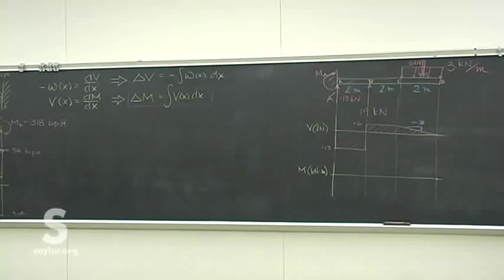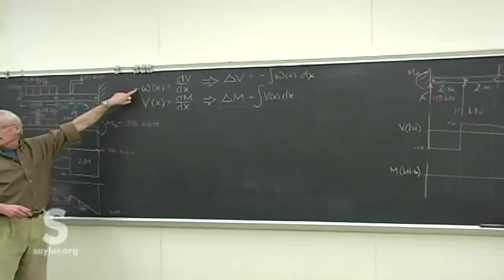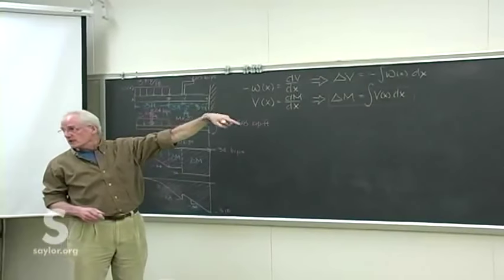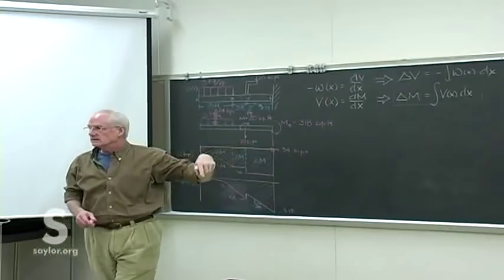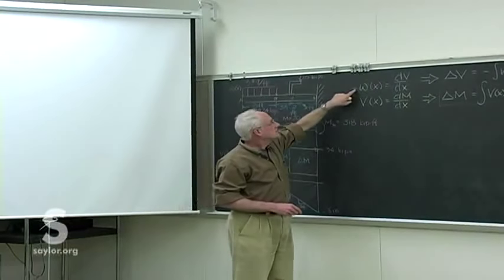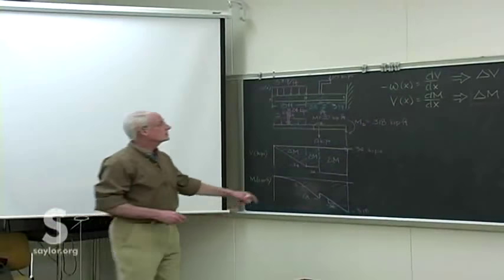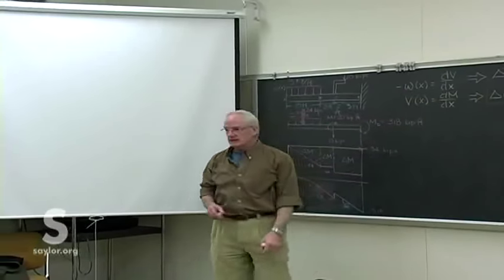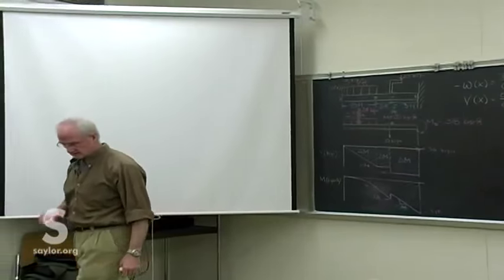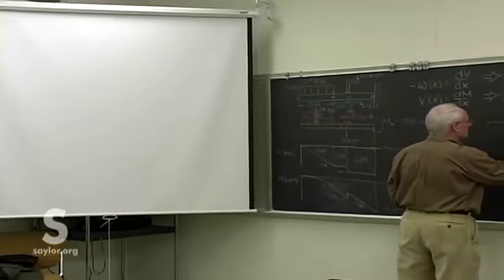Because of this right here, in our rotation, a distributed load down is considered a positive load. So we put a negative on it, and then the slopes match. That's the only one of those relationships that has a negative sign in it. Well, I guess it's equivalent one of delta V does. And that would all match with our convention of positive directions.